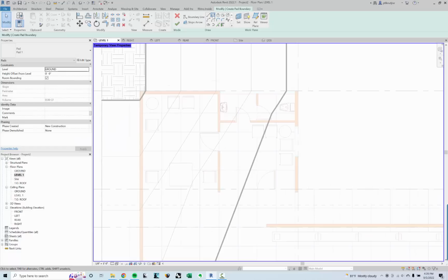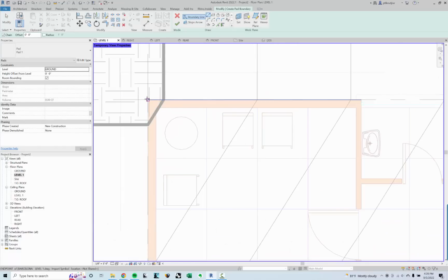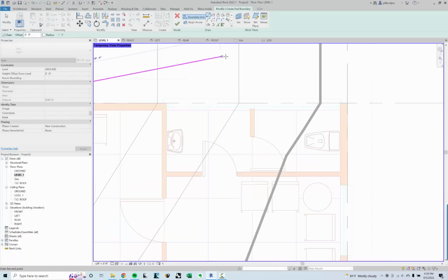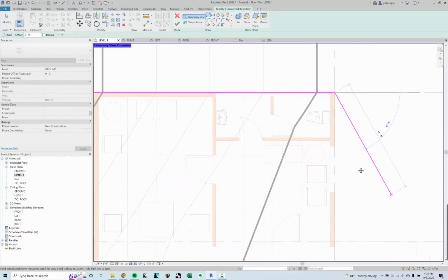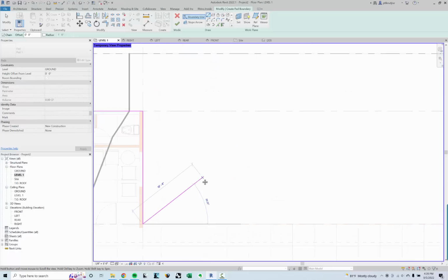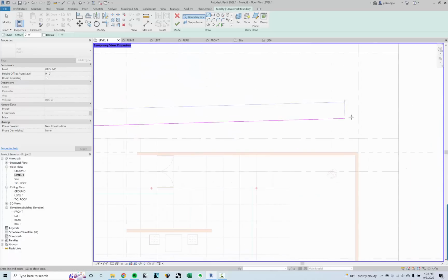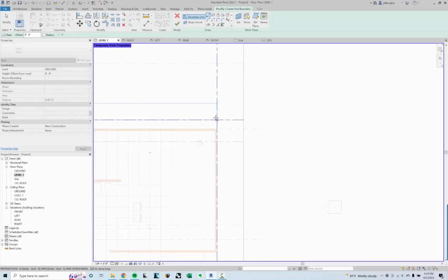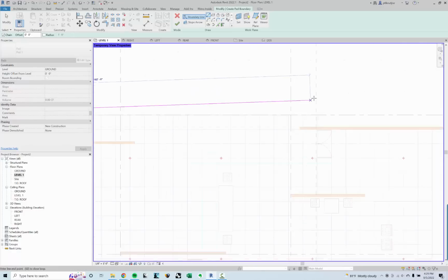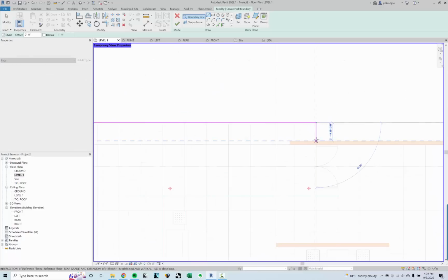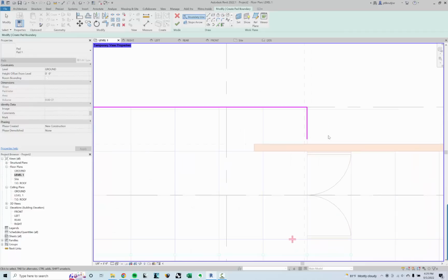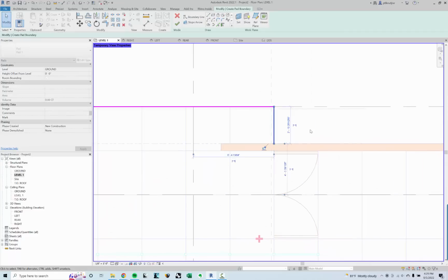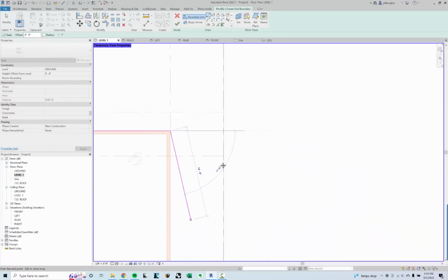And I'm just going to do my building pad and I'm going to draw it using lines. We're in what's called sketch mode now, like we did for the property line. And I'm going to click from there to there, to there, to here. Wait, actually where? Oh yeah, sorry, to here. Then it steps in. I'm going to escape out and then just bring that down to clean that up. And then I can come back into here.